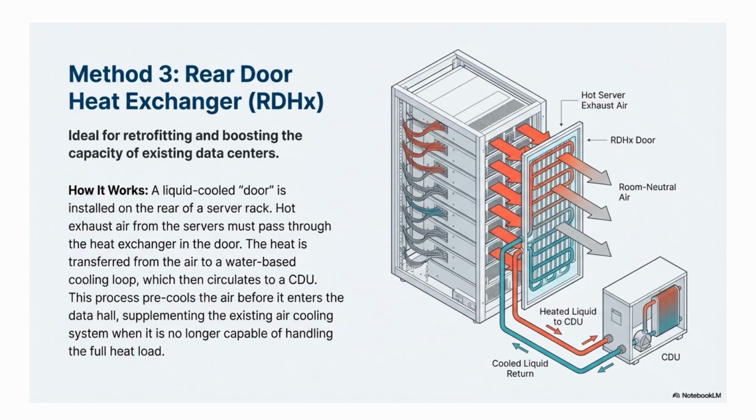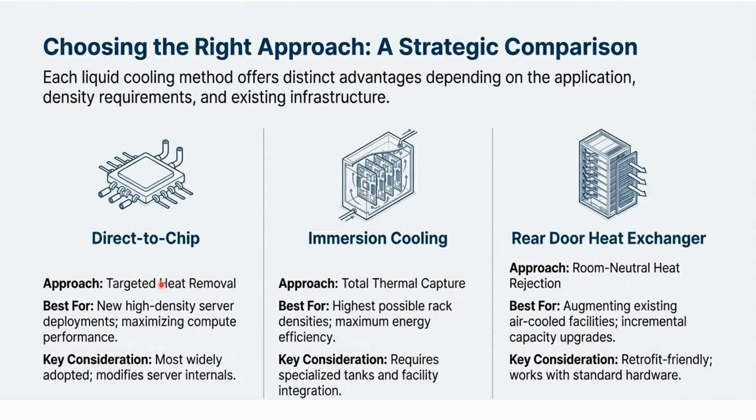That really clarifies the landscape. DTC for precision, immersion for density, and RDHX for a pragmatic retrofit. I think that's a perfect summary. We've walked through the mechanics and the trade-offs. To recap, DTC is surgical, immersion is total, and RDHX is supplemental.